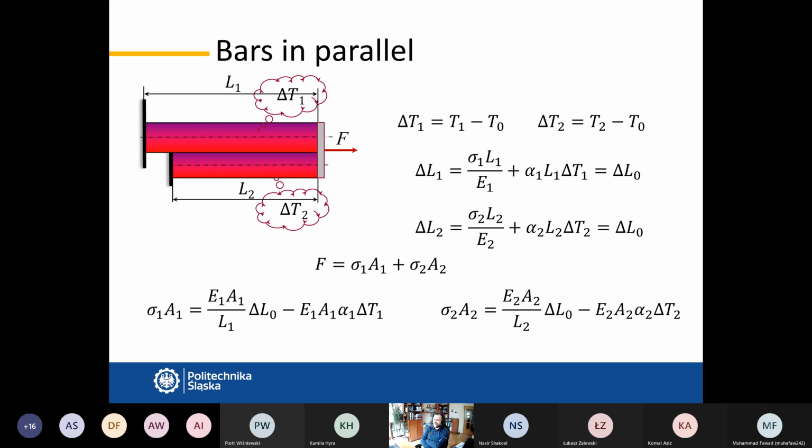And we can slightly release this reaction by two possible actions. One was the thermal gap between the supports. So the object does not exactly fit into the area, but there is a slight gap between, let's say, the wall, the constraint, and the object.